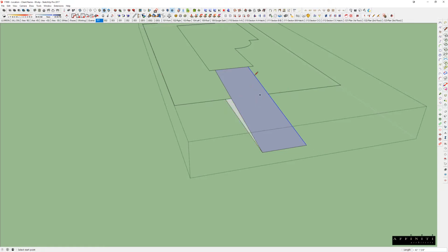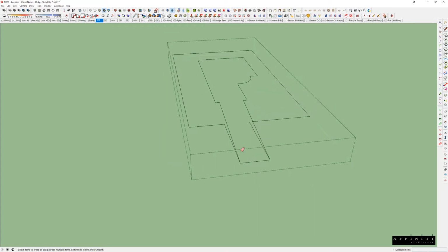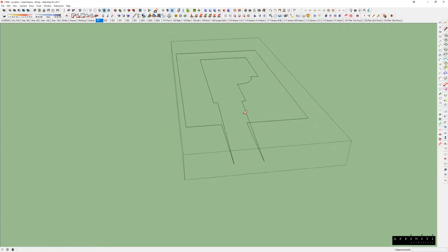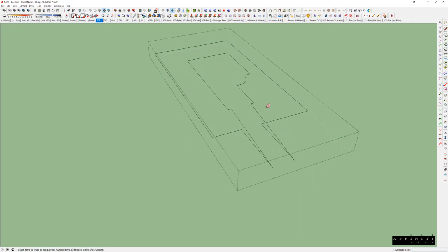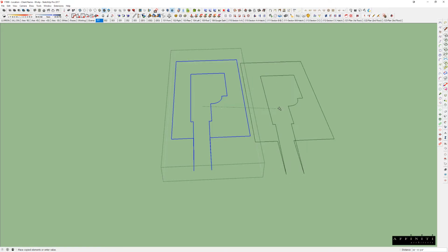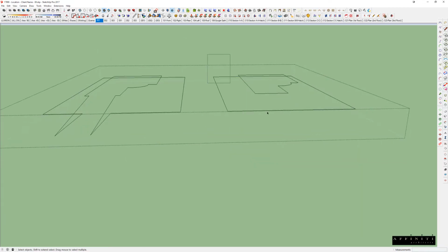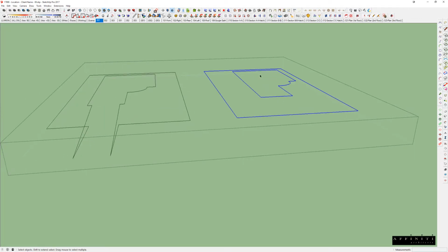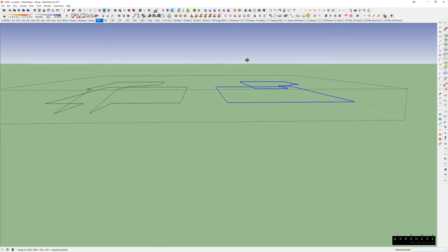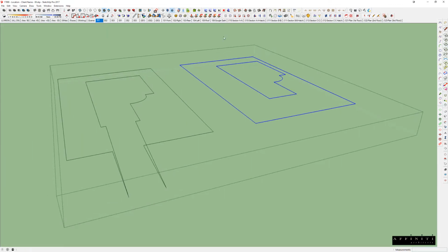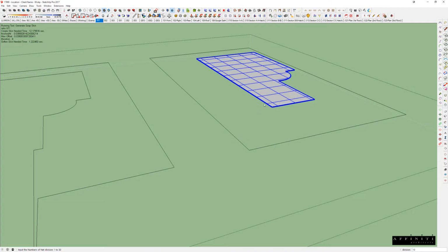And if you don't know where I'm going with this yet, ultimately we're trying to create a closed loop for our Soapskin Bubble to use. Now, the driveway is a nice breaking point, because if I didn't do it, and I go back to this, let me draw this back in. So I have this. Just like before when I tried to do the double set of contours with Soapskin, this is going to see it as two different closed loops and will say it won't work. So if I click on Soapskin, it's just going to do the one, not the both, because I don't care about this. I want to connect from here to here.